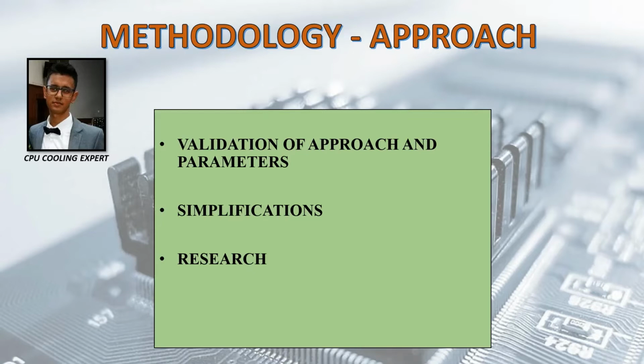The CPU was modeled as a thin silicon solid with isotropic properties. The inlet was also modeled as a free stream instead of a fan. In order to compare different geometries, we need to keep all other parameters the same. The environment for both heatsinks has to be identical.